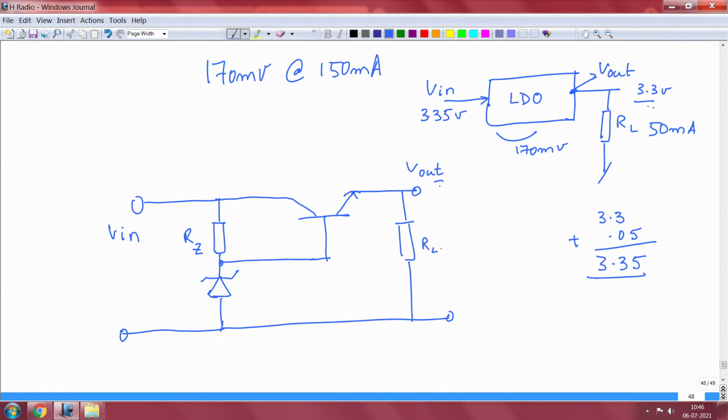The good thing about this circuit is that it will keep you well within regulation, okay. You have connected the Zener diode at the base. What you will get is a, from the old transistor technology, you will get a drop of 0.6 volts. If you have 5.6 volts here, you will definitely get 5 volts and it will be stable.